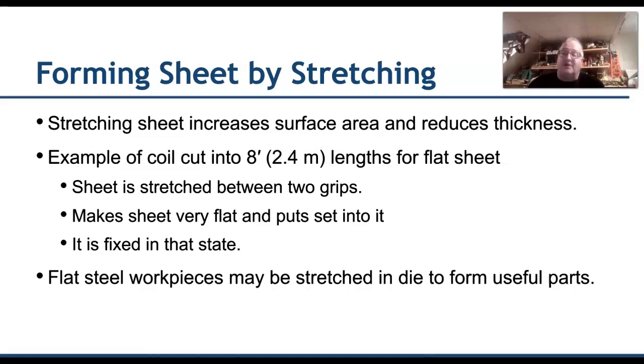That's going to increase the surface area and of course reduce the thickness. Some examples of this: oftentimes your steel cans, or even your aluminum cans, can be stretched over different types of forms, and we have to pay attention to how that stretching is done. We're starting with different thicknesses, and of course we account for the finished thickness at the end in those processes as well.